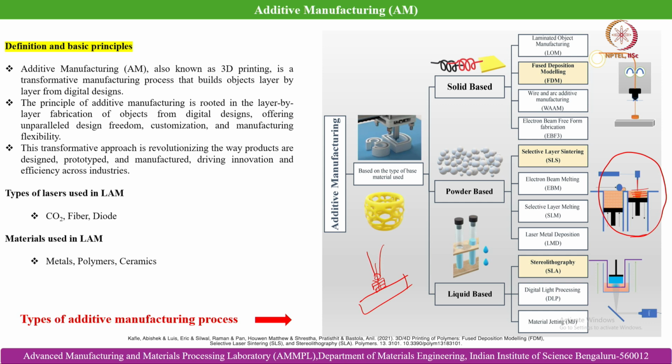So, in case of developing a complex contoured micro part, I would say that LPBF is a much better technique than DED, whereas in case of cladding or in case of a repair, you can very well go for DED with cost efficiency and economical aspects in mind.